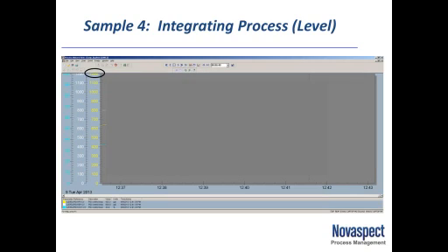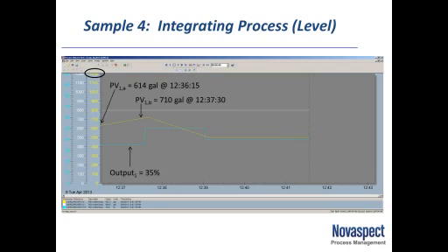So this is an example of a tank level. We said a full tank is 1,200 gallons. Now this could be 0 to 10 feet is our tank. It could be 0 to 180 inches. It could be in gallons. It could be a lot of things. I just want to point out that when we're doing the math, we need to rescale to percentage scale and not use the engineering units directly.